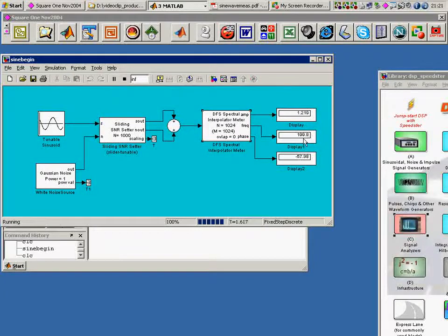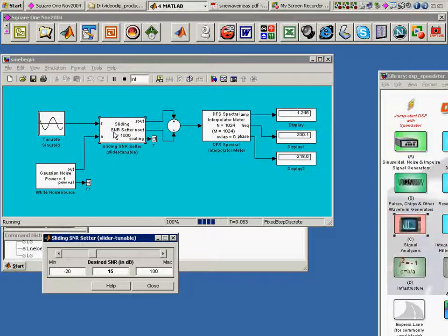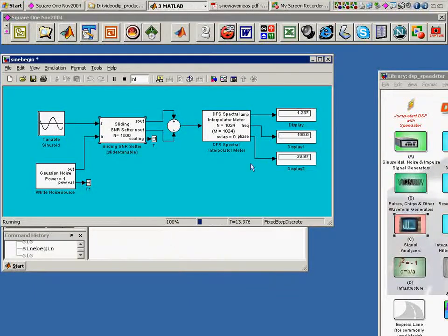what we see is a pretty stable frequency estimate, amplitude jumping around a little bit, phase jumping horribly all over the place. Maybe it's to do with noise. Let me crank up the signal to noise ratio up to 100 so that effectively I've got a noise-free situation. I look back over here, I'm a bit bemused to see that in fact the frequency is stable as it is, but phase is jumping around just like it was before, now in a noise-free case, and even the amplitude not completely steady. Makes me wonder, first question is, what is the true answer?